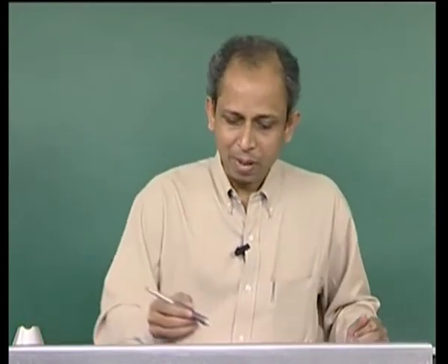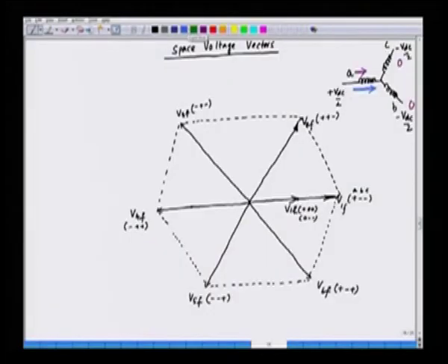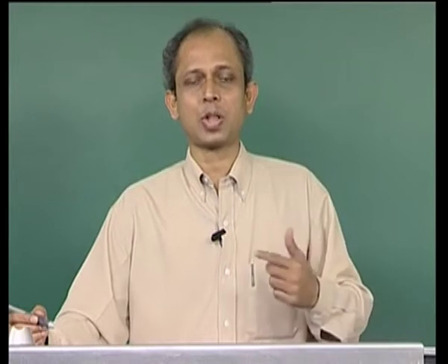We can have the same voltage vector by having 0 in phase A. So, we can have another possibility that you apply 0 in phase A, but apply minus VDC here and minus VDC by 2 here. So, in this case also the effective vector is minus VDC by 2. So, it is again minus VDC by 2. So, again it is half. So, we have two possibilities. It means the half voltage vector can be obtained by two possible combinations.